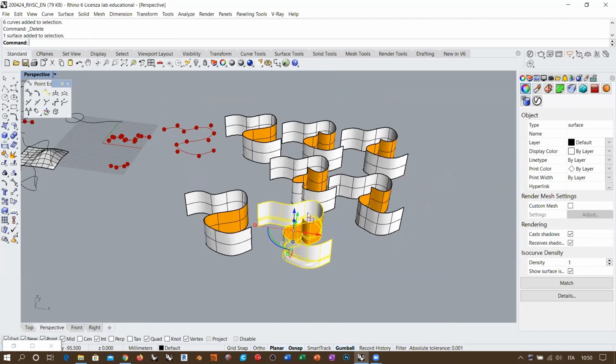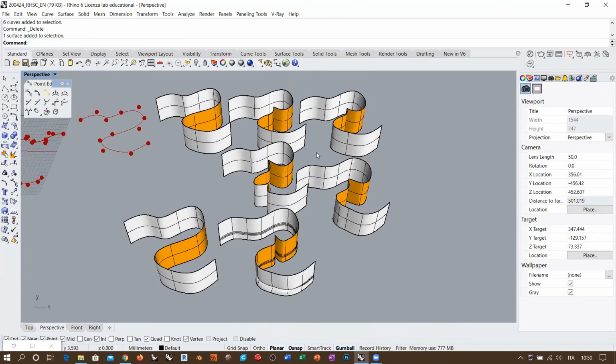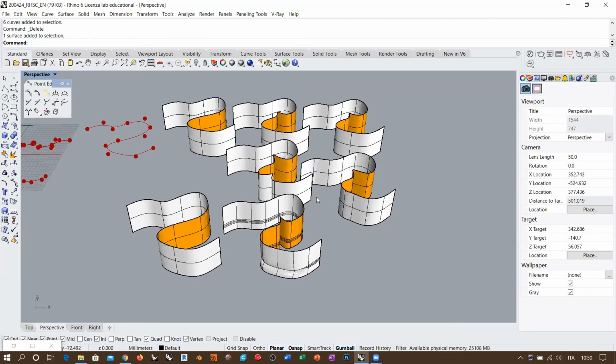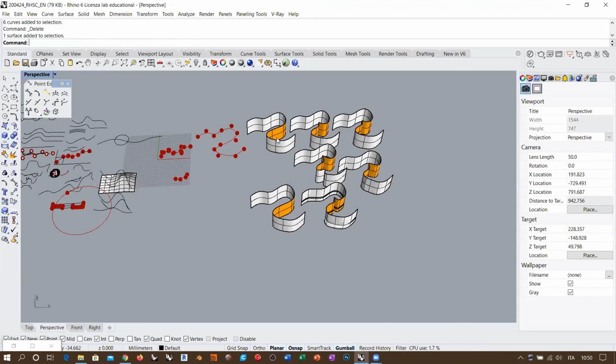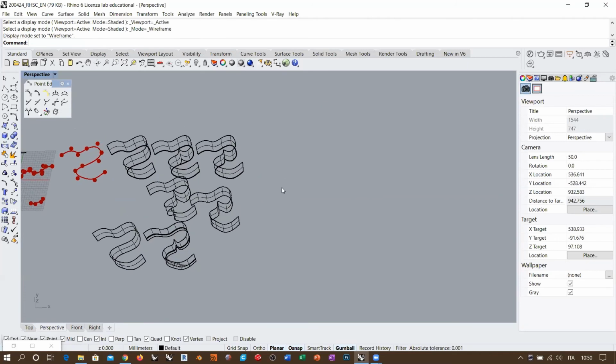So it's absolutely convenient to create invisible kinks in areas where you want some crease happening, and eventually deform the shape after having created the internal discontinuity. So keep it invisible. Creases are also very nice techniques to create some interesting shapes.